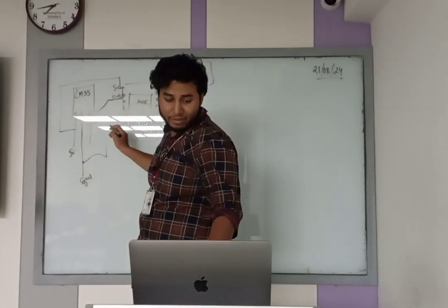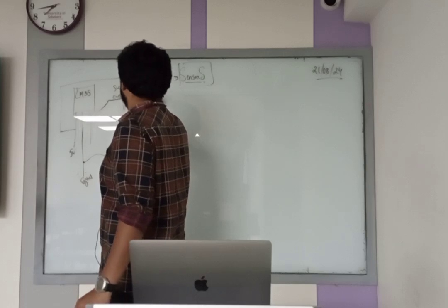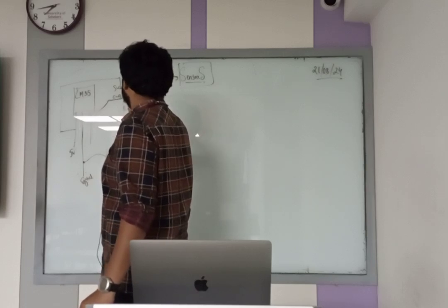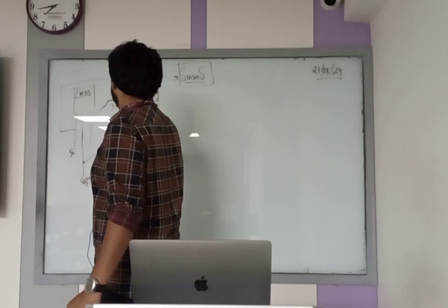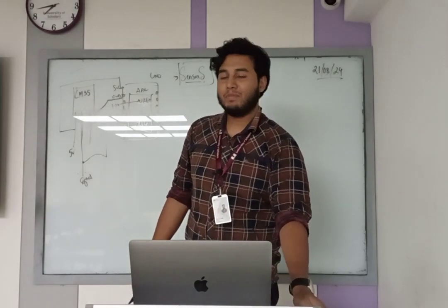So now we have to focus on how we connect and how they react with each other. There's obviously a reference pin over there, so it's ADC and VREF. It's not necessary to connect it with the 1.1 volt, but it's convenient whenever you connect this 1.1 volt with the reference pin. So that's how you can connect with this, what? LM35.